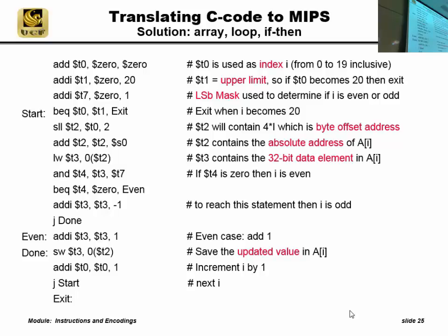But in embedded systems, you can also look at the I/O components, and you can send bits out to an I/O device. It makes the motor turn, or makes the LEDs light. Same thing. So take a look here. If we want to access a certain address, this is converting from index to byte, and then adding the offset. So at that point, T2 is ready to go. We just need a 0, which is great because it has to be a constant.